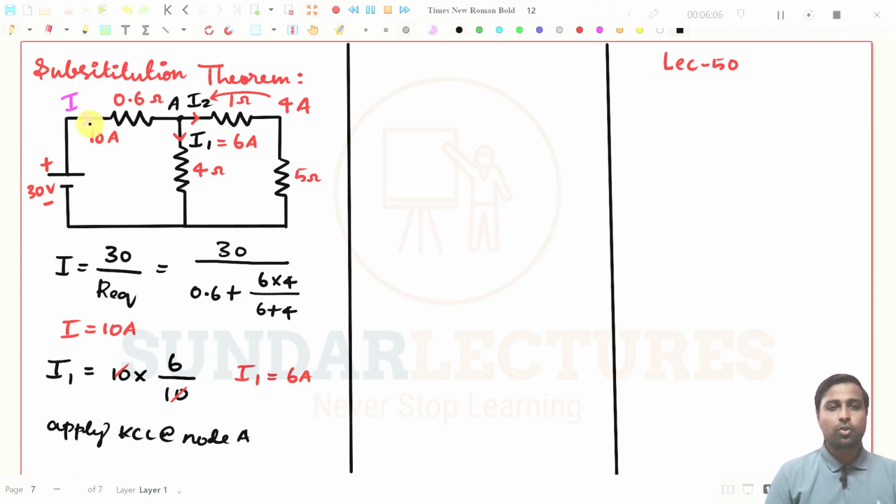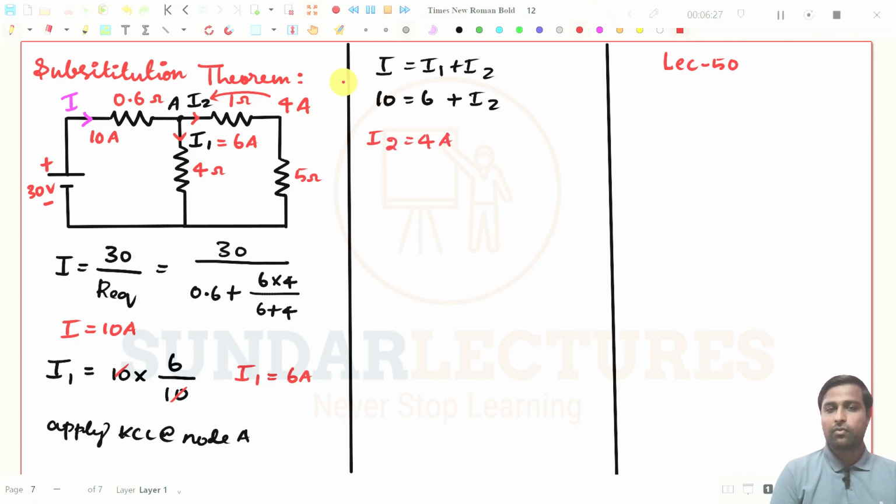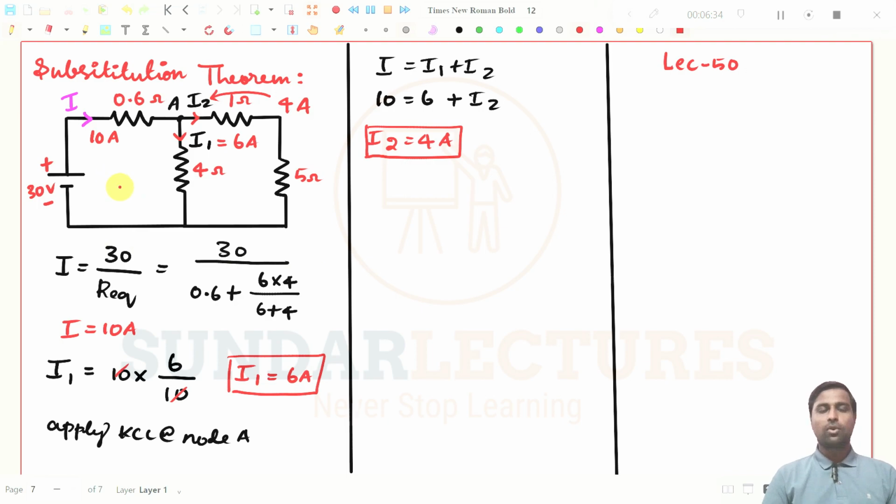So KCL. I is coming in, I1 is going away, I2 is going away. So I should be equal to I1 plus I2, and this is 10 amperes we know, and I1 is 6 amperes we know. This should be equal to I2, and finally I2 will be equal to 4 amperes. And I1, this is 6 amperes, we have found already. So now we know what is the current through all the resistors in the network.